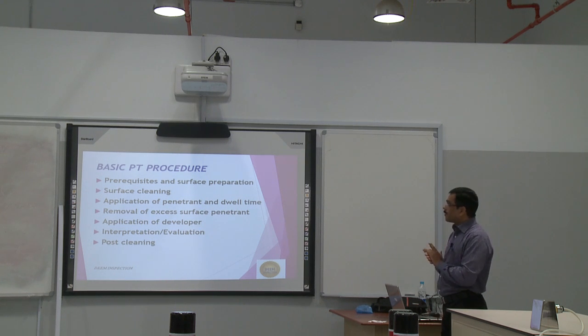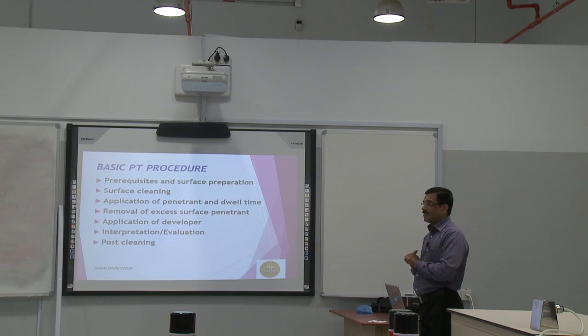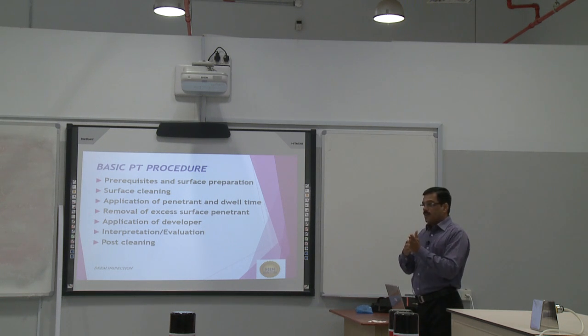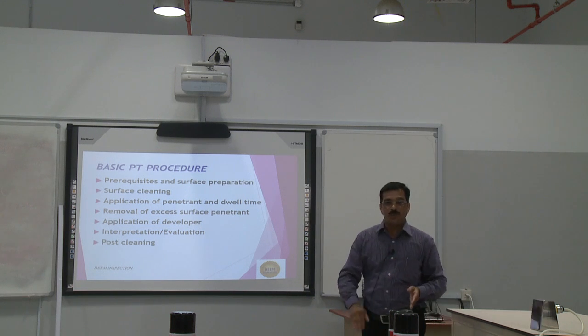About the prerequisite, the surface preparation. If I have some bar, I weld it, and I directly do the test? First make cleaning for the surface, or machining, and after that you need cleaning. Yes, after that we have to do cleaning. Because for surface preparation, suppose on a weld surface, what are they doing? They are doing some grinding or wire brushing. It is as welded condition. Now this is a test piece.